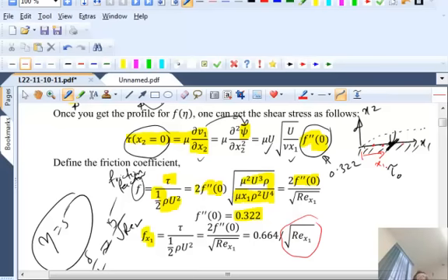How can you measure that local shear stress or local friction factor? It simply means that at every point the force exerted by the fluid on the plate is decreasing. So if you take a point farther downstream, the force exerted by the fluid locally on that point is going to be smaller than the force exerted by the fluid near the inlet. But what we can easily measure is the total force. I can easily put this on a spring-mounted device where, by looking at the extension of the spring, I can find out the net force exerted.